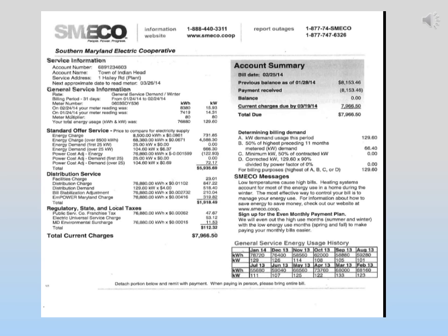What they are telling us here is if we take a reading and multiply by 80, we will get the actual usage. The kilowatt hours, total energy usage, was 76,880, and the demand was 129.60 kilowatts. A rough ballpark we are dealing with here is somewhere around 100 to 125 horsepower worth of equipment that was running at the same time for the designated time to establish that demand.